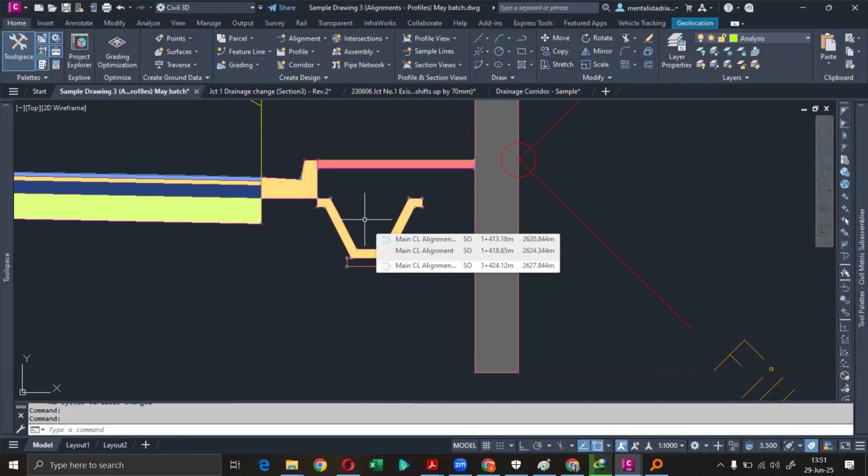First of all, the reinforcement that you're going to put on that drainage is going to be too much. Elsewhere, I don't have to do a lot of reinforcement on the drainage because people are not passing there. And then you find buses passing on top of this thing, not knowing that it was not made for that. If you're going to put a drainage under the road, just know that you're going to spend a lot of money to reinforce it.